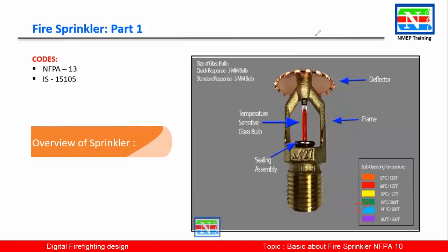This one and 1 2 kg extinguisher they are providing in residential building most of the time. No, even residential, they'll provide extinguisher. They will provide a sidewall sprinkler, and a 2 kg extinguisher. That 2 kg only I have seen most of the time. CO2 extinguisher, what you saw in the previous slide.